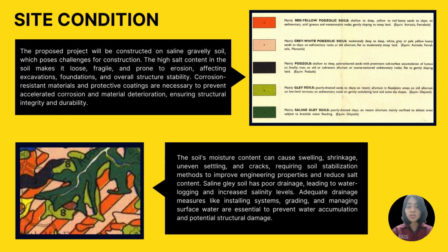The high salt content in the soil makes it loose, fragile, and prone to erosion, affecting excavation, foundation, and overall structure stability. Corrosion-resistant materials and protective coatings are necessary to prevent accelerated corrosion and material deterioration, ensuring structural integrity and durability. The soil's moisture content can cause swelling, shrinkage, uneven settling, and cracks, requiring soil stabilization methods to improve engineering properties and reduce salt content.